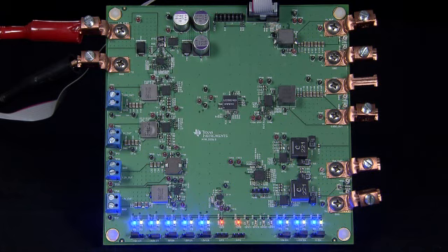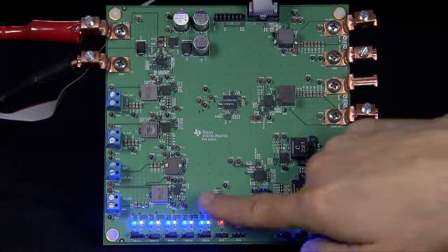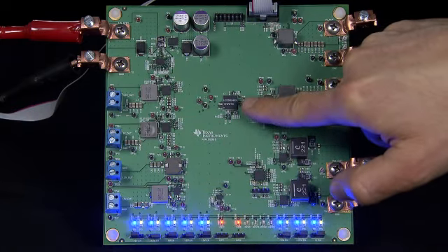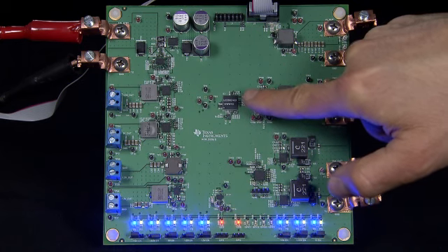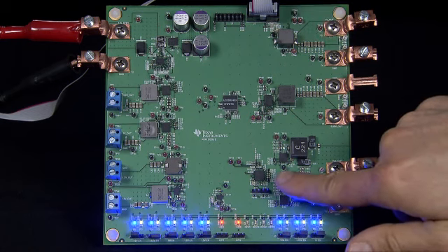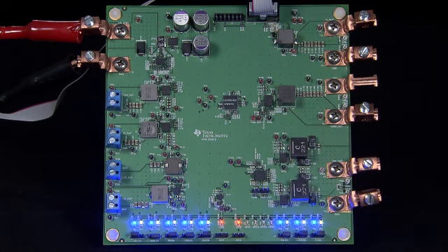On this board, as we mentioned, you will see we have the 12 volt input coming in, the 12 volt PMBus hot swap controller that provides not just protection for the rest of the card, but also PMBus monitoring of the input voltage and current, the four analog voltage regulators that are sequenced and monitored through the UCD90240 24-rail PMBus sequencer with black box recording capability, and then the three PMBus voltage regulators, two 30 amp PMBus converters, and one dual output or dual phase PMBus buck controller.